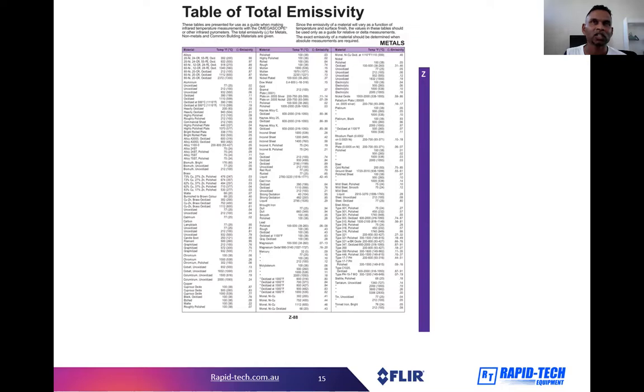So by just changing that surface property, by applying black paint or gaffer tape onto that surface, that surface is now going to emit its infrared energy. And that's when the thermal camera will pick that infrared energy up. All right, so again, there's limitations, as I mentioned, with thermal imaging, but there's ways to work around it. If you can change the property of the surface, that helps.